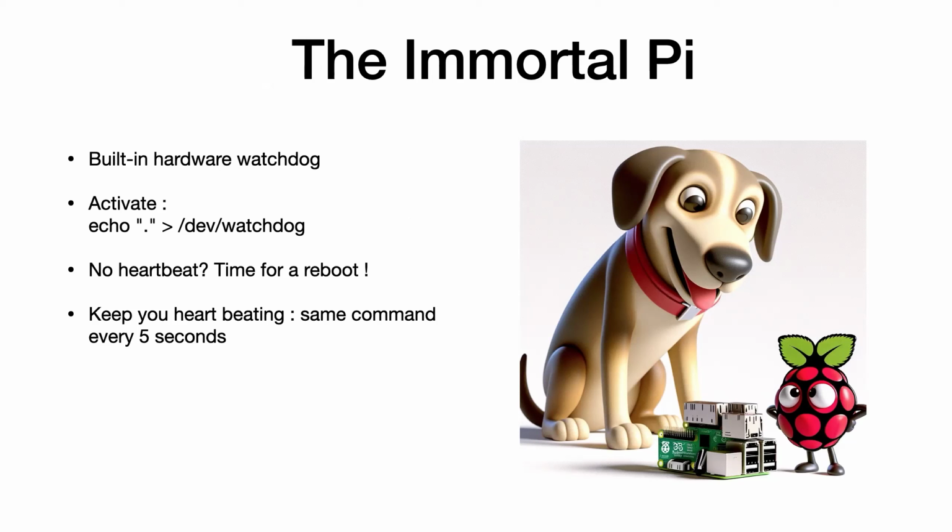When you want to stop the watchdog, very easy. Echo a capital V to that same device driver, and that's it. Fido goes back to sleep, and everything is cool.